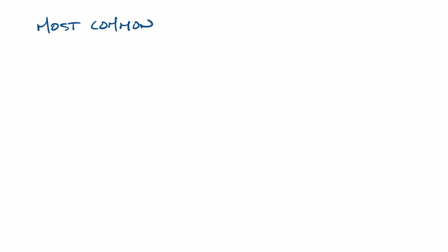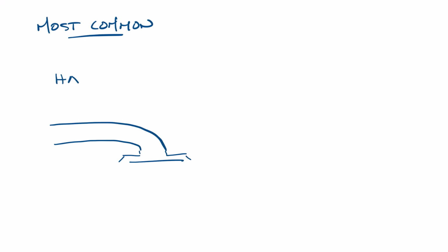What we probably see most often is flex duct laying across the ceiling and turned over into the inlet of the diffuser. This hard 90 will do a couple things. It'll add 5 NC to the catalog data, bringing our diffuser up to an NC30. But it also can affect the airflow of the diffuser.